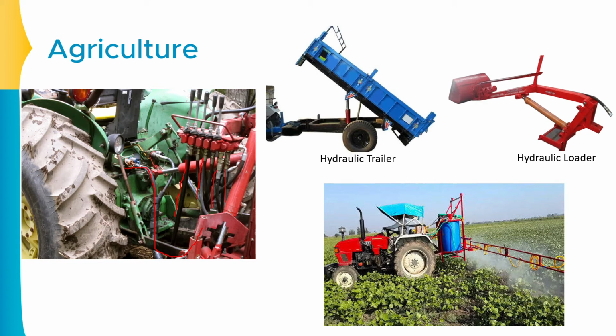They are the hydraulic lines if the tractor has a higher hydraulic application, or they may be pneumatic lines. Now what is the purpose of this? They are basically transferring the hydraulic or pneumatic pressure to the equipment attached to the tractor. The equipment may be mowers, ploughs, chemical or water sprinklers, fertilizer spreaders, harvesters, trailers attached to that specific tractor, or a hydraulic loader. Each and everything can be operated with the help of this device.